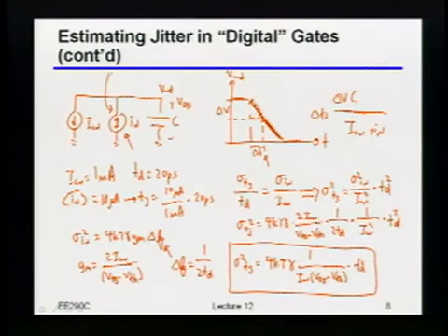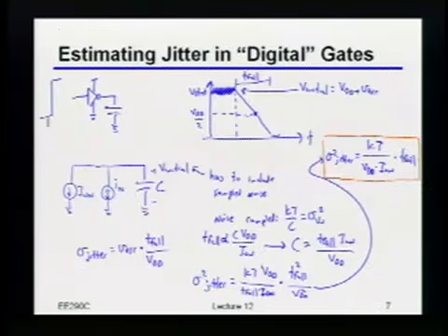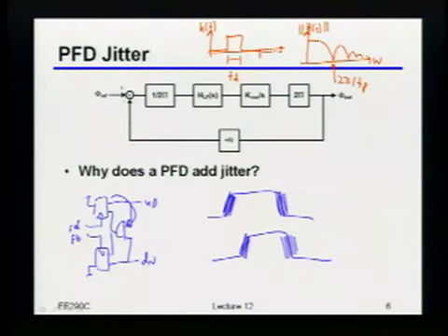The assumption I'm making here is that indeed the input into the inverter is a step. It's not exactly true, but that's close enough from an analysis standpoint that we'll get a very reasonable answer. Second question was, for the sinc function, you do mod square df? That's right, I'm just doing the standard noise integral of the integral of |H(f)| squared df. It's just the noise bandwidth, exactly. I'm just figuring out the effective noise bandwidth due to that box filter transfer function.